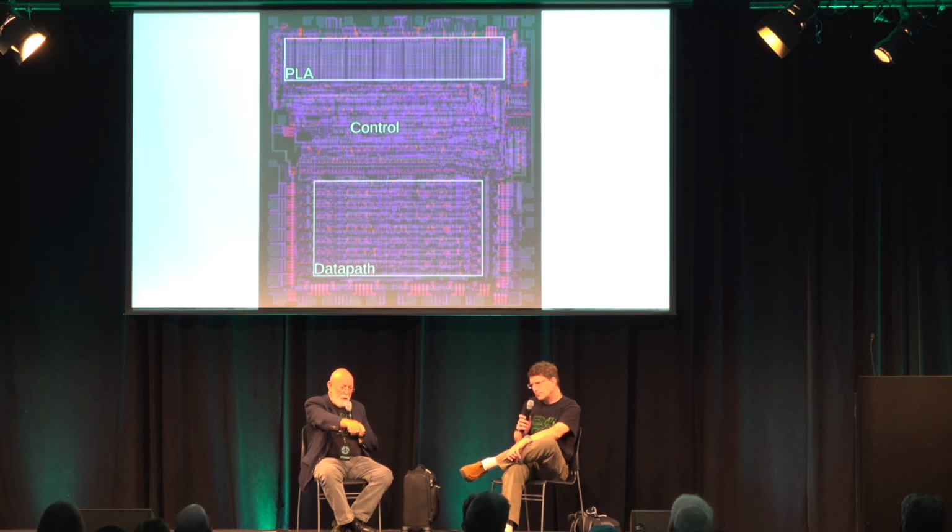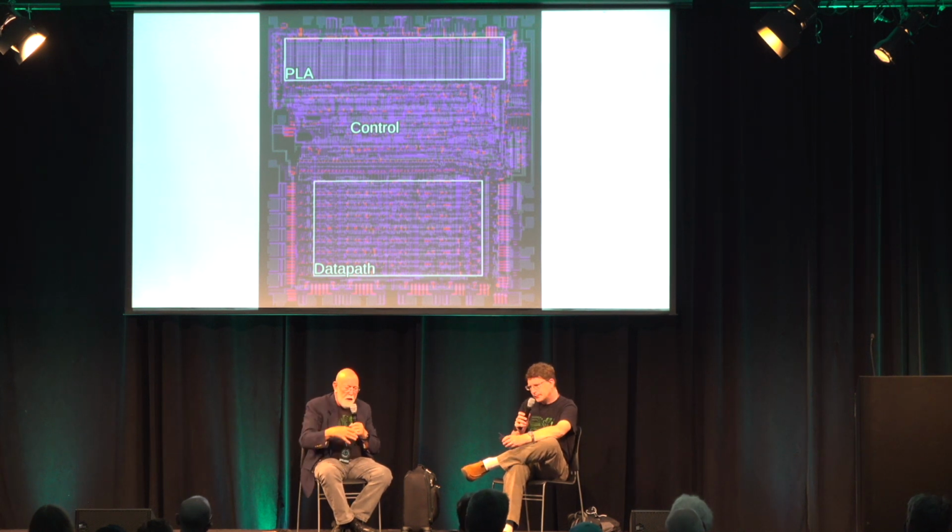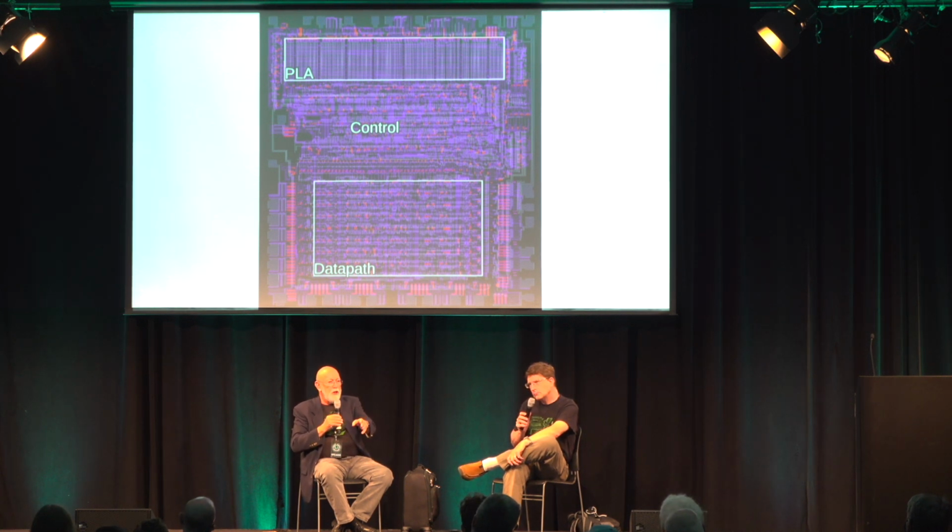So the timing generator there on the left of the PLA is three bits of a timing generator. So we could go through timing state 0 to timing state 7. And so we had to go from that pre-decode over there to stop the counter from counting to the next. And you're referring to the program counter. I'm sorry, the program counter's here in the middle. But anyhow, so we had to stop that. But what we also did was we could go over there and change the timing state.